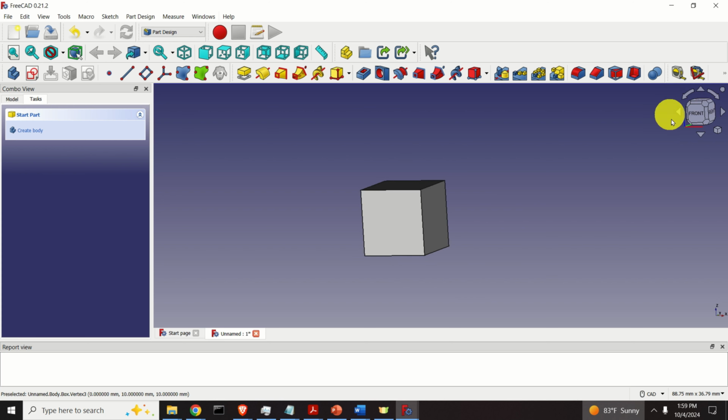Here's our rectangle. Next, we explain how to precisely define the length and the width of our rectangle. Currently, we're in the rectangle mode, so press Escape to exit. Then, select this edge, then click here, that is, click on Constrain Vertical Distance, and over here enter the length of this side or of this edge. For example, let's go with 140 millimeters, and then zoom out to see the scaled rectangle, and let's define the width.